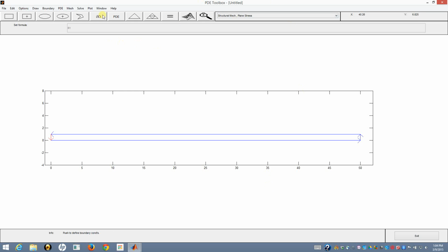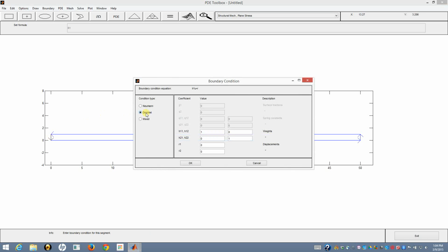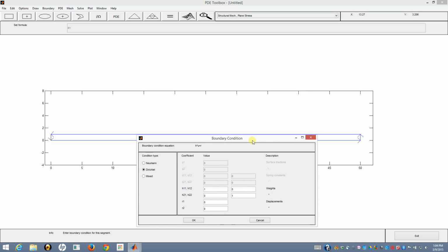Okay, so if I go to the one that's the boundary term, which is this one right here, if I double click that one, I've got, drag it down so I can walk up to it. So I've got H times U is equal to R. H is just the identity, so that means just U is equal to R. So I've got no displacements, and along this edge it's fixed, it's just going to be welded completely to the left wall there.